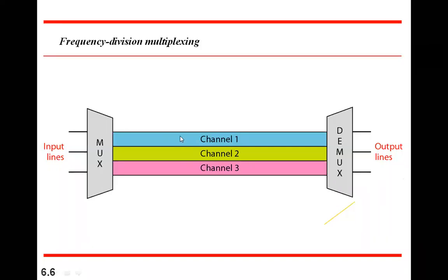But what is the advantage? That channel is available continuously for the user. All the time it is available. So you can continuously keep sending at the rate of 10 megahertz, as per our example. So that is the difference: the total spectrum is divided and each person is allotted a part of it. That distribution can be uniform or need not be uniform. It depends on the administrator. Whatever way he is interested, he can allot it. But basically that's how frequency division multiplexing works.